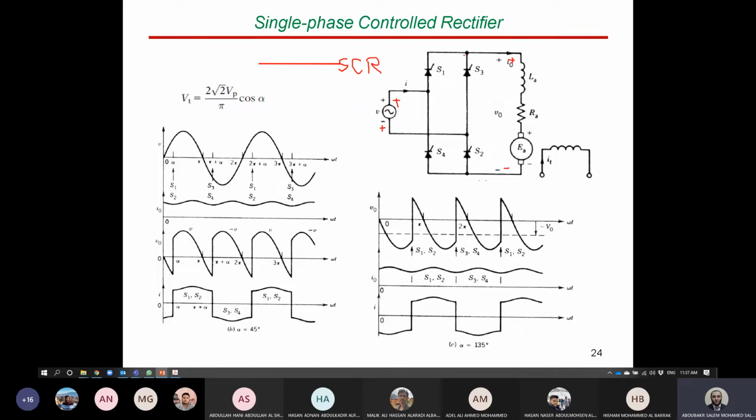Right, how this rectifier circuit is working exactly, how this thyristor is working, let's discuss it here in the waveforms. Here we have a type of circuit, guys, called the inductive load. Why is it inductive? Because we have RL in the circuit. So the AC source will see an inductive load all of the time, whether the motor is DC or not. It's some coils, and the AC source will see that these coils are considered as an RL load.